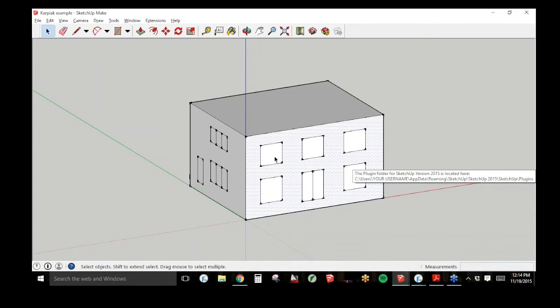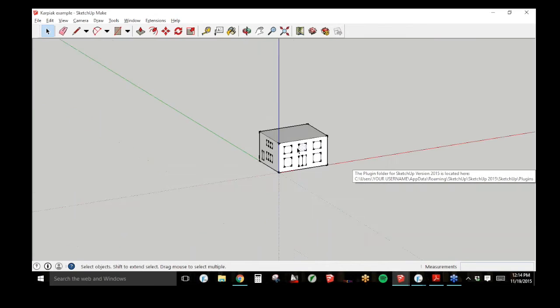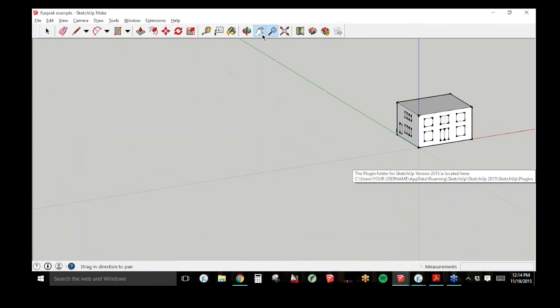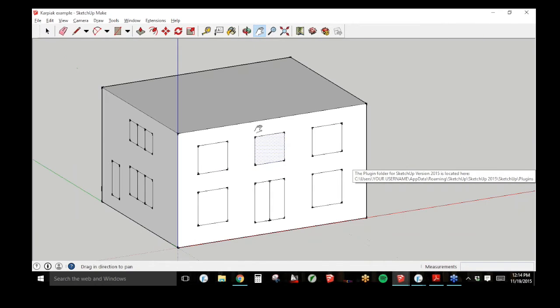When looking at windows, it's important to note you don't draw the window frames. Each of these components becomes an imported component in WUFI Passive. So we build in from the exterior dimensions here. You pick either the rough opening or the window dimension, probably window dimension. It shouldn't be too different. So we draw in from that in our WUFI Passive model. So you always do the whole window dimension, no frames.